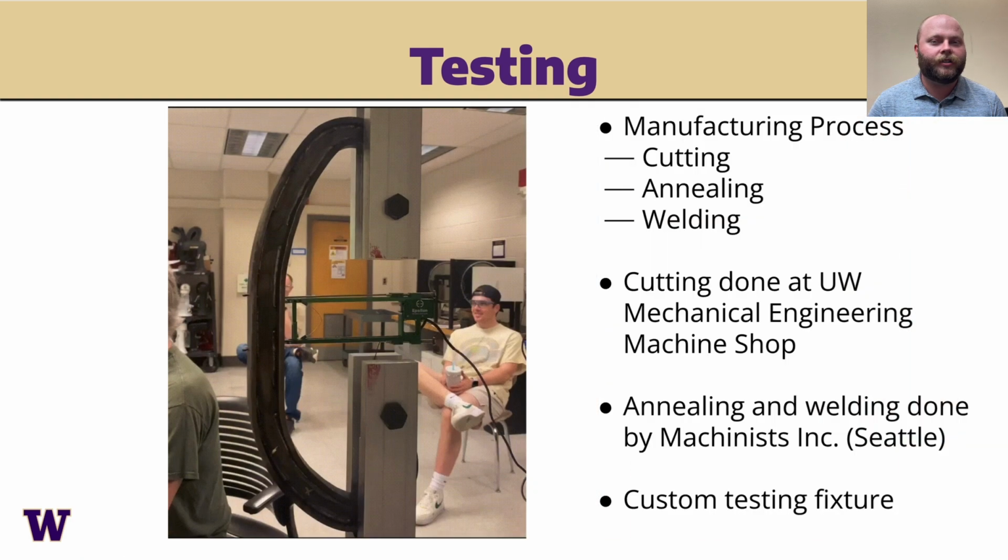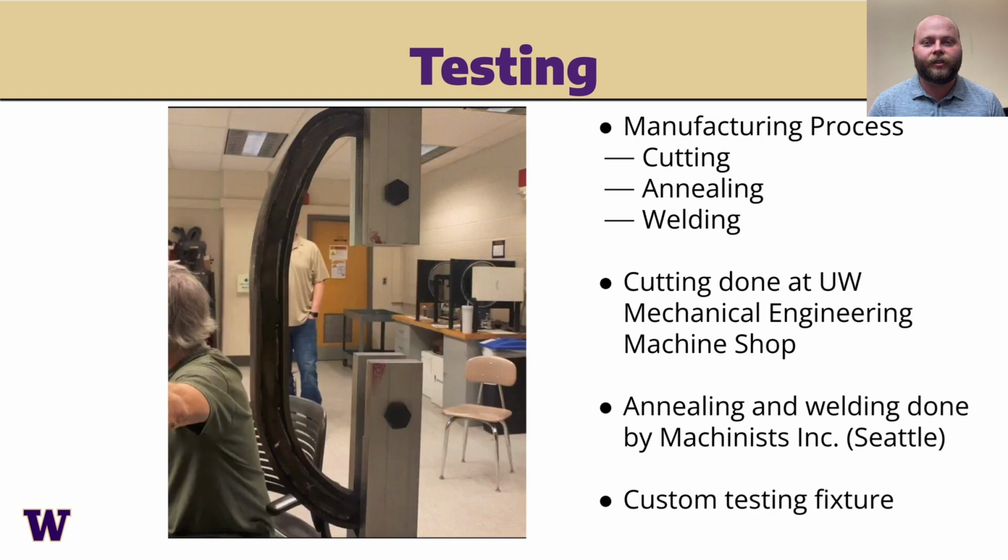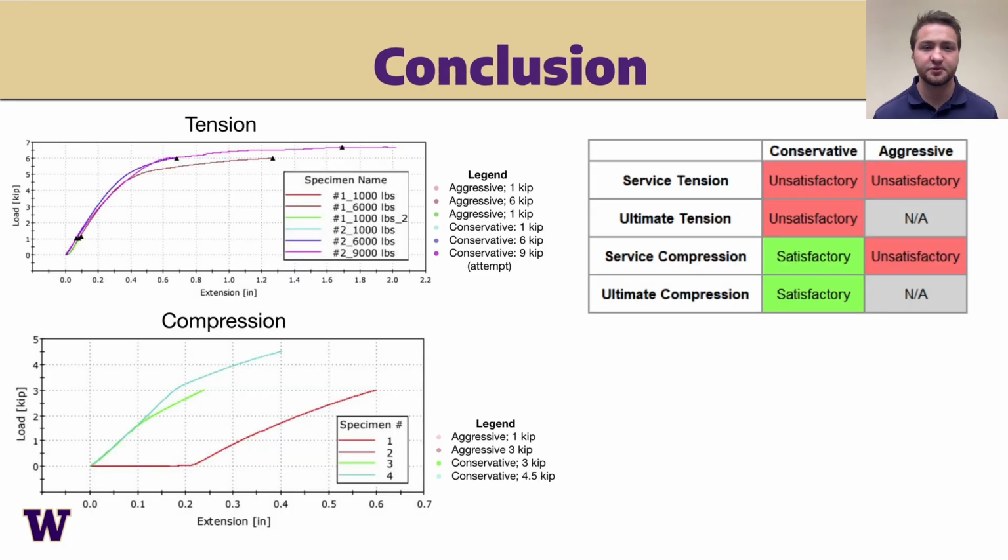Here are hinges being tested in the Mechanical Engineering Building's Instron machine. Upon testing, we found both hinges to undergo yielding much earlier than predicted by our theory. The initial response resembled FEA quite well, and you'll notice that elastic behavior continued as predicted. We would achieve acceptable deformation.